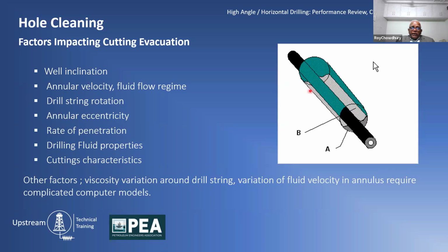Is your drill pipe sitting right in the middle? Because remember, in a high angle wellbore, most likely it is sitting at the bottom, so it is creating these channels. If that's the case, along these channels, the cuttings are settling.